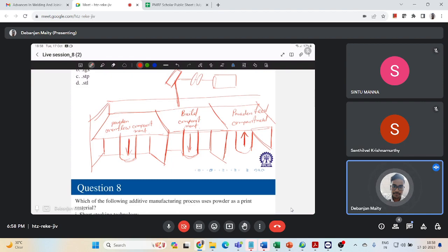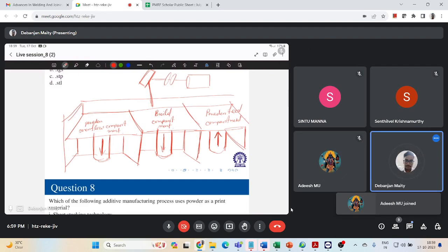So this powder bed fusion system forms the powder bed by continuously rolling the metal powder from the metal supply bed onto the build platform. These are compacted cylindrical particle layers, between 20 to 60 micron thick.